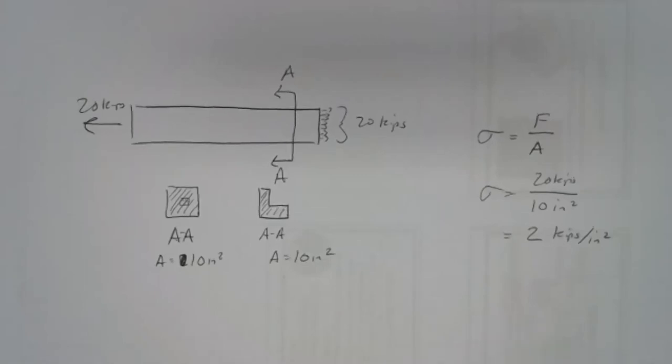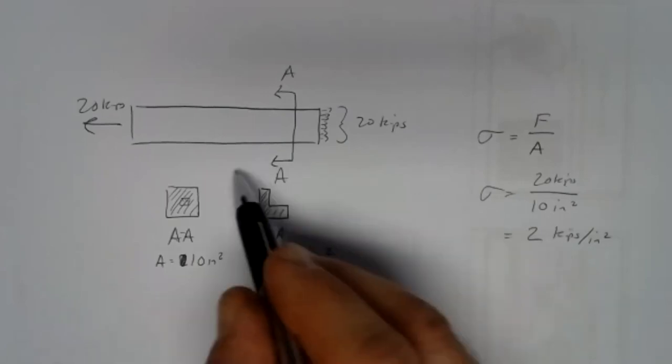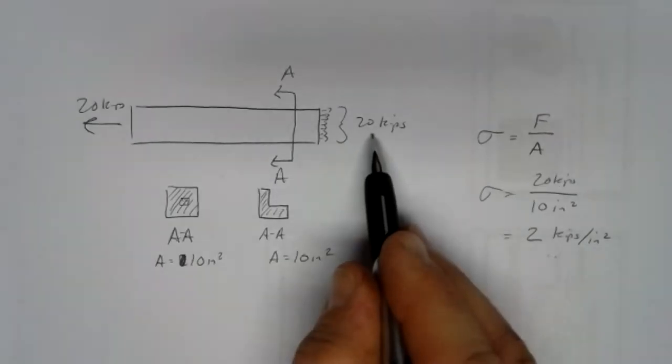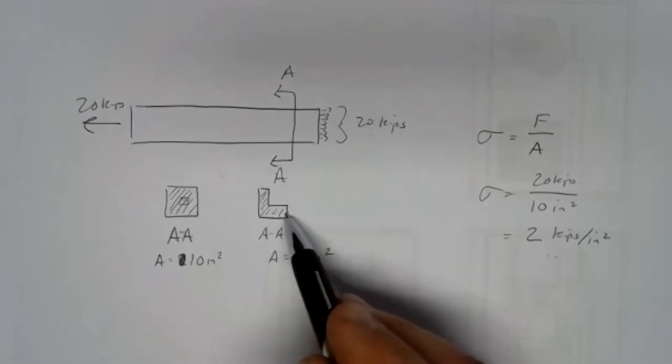It also makes it so that when we look at limits, and we'll be looking at material limits at some point, the ultimate strength, how much stress a piece of material can handle or a member can handle, comes down to the stress. It doesn't come down to the force. The force depends on the details of the shape.